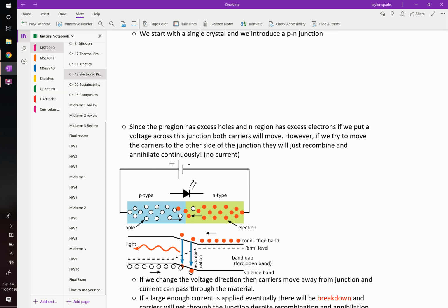That's a transistor. Okay? By the way, this is the exact basis of a photovoltaic, a solar cell. Every single solar cell is just a PN junction. You've got a material which is P-type doped and N-type doped. It's just the exact opposite. In comes sunlight, so instead of light being given off, you have sunlight coming in. It hits one of these things that are in the in-between region. We call this the depletion region, where these things come together.